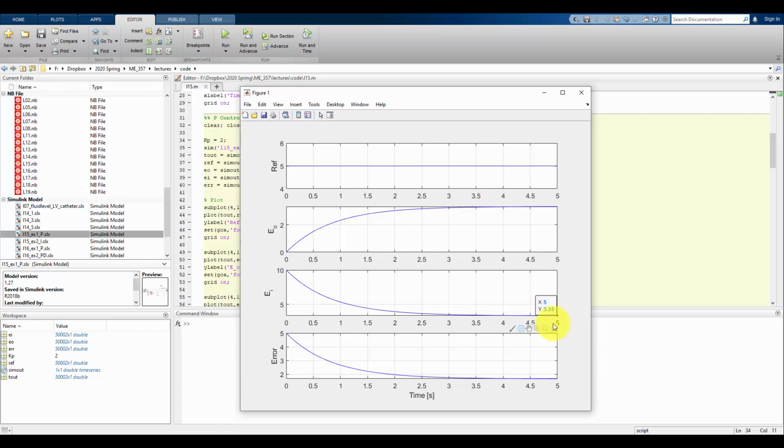We're still not there yet, and we're paying a penalty, or a trade-off: initially, at least, we have to put a much higher voltage into the system, 10 volts. And we see that the system is responding more quickly because tau is getting smaller as k increases. So the response time, or the time constant of E out, is faster.